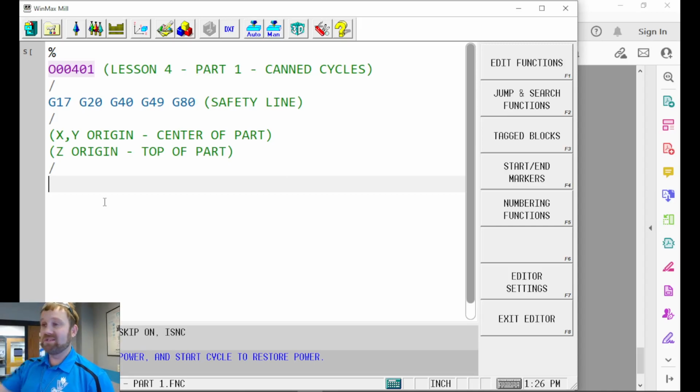Copy, paste, modify. We do that in Mastercam. If I've got a good toolpath that works, I'll copy it, I'll paste it in, I'll change the geometry to whatever geometry the part is, I'll make linking parameters or depth adjustments if I need to, regenerate it, move on. You don't have to start reinventing the wheel every time, all right?